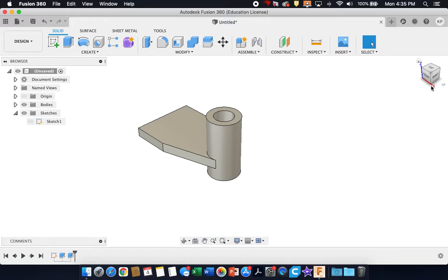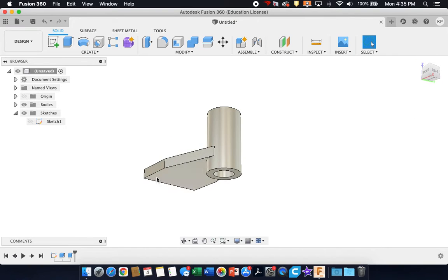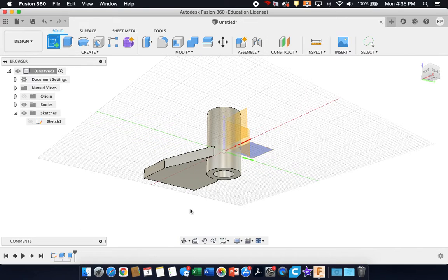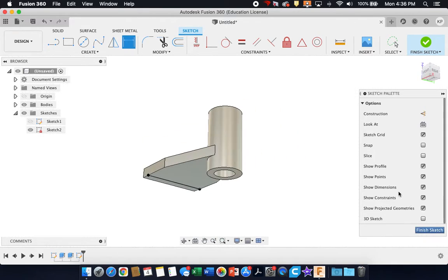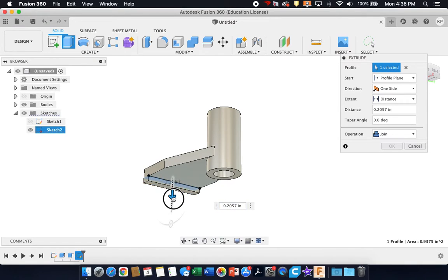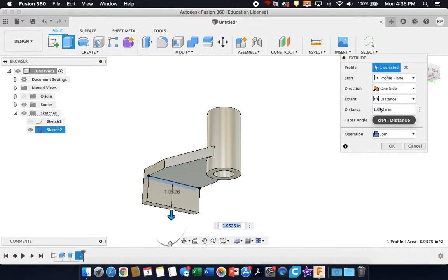Let's go ahead and on the bottom, we want a 90-degree here, so we're going to create a sketch on the bottom. Going to use our line tool, and sometimes it's hard to get it to snap to perpendicular, so I'm going to purposefully make it angled the wrong way. Use my constraints, horizontal, vertical, change it, and dimension this 0.375 away from that back edge. E for extrude, select that. We want to go down this direction, and we want to go a total of 0.75.